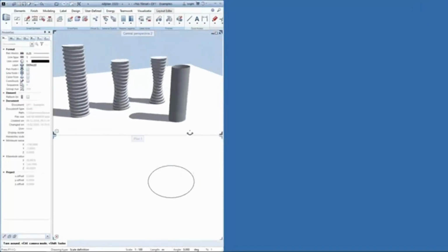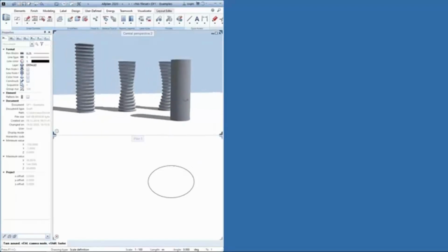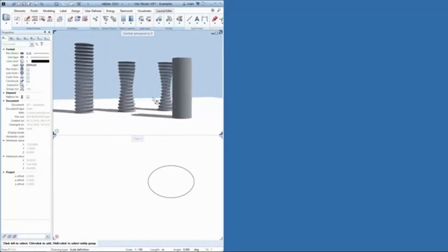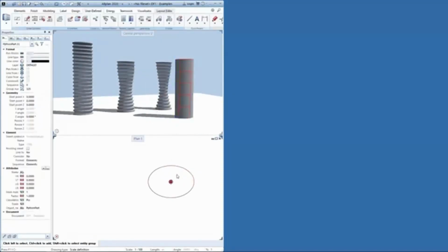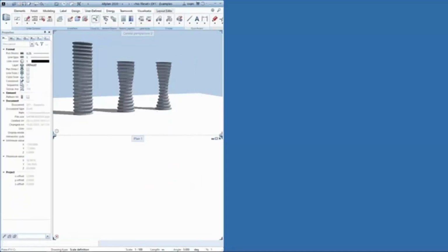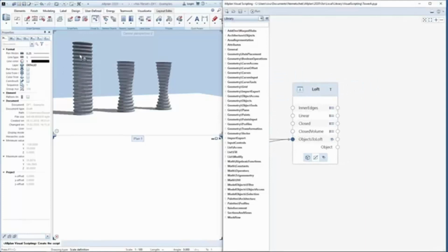So now it's correct. But as we say this is a glass facade, it should have some material on it, or it should be translucent. So we should give it some material. So let's delete again, create object, open the VisualScripting. As for the normal object from Outline, we have the option here to change the format.